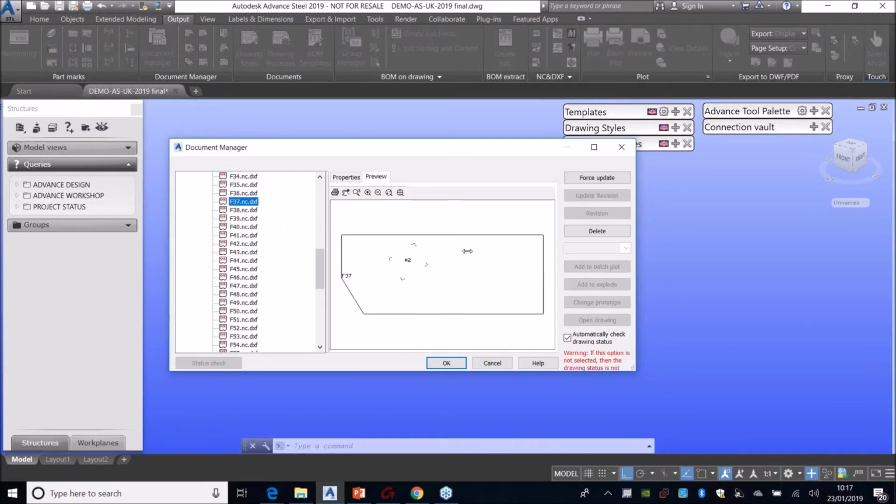All right, so it's not necessarily a base plate, but we do see an intersecting member, rectangular hollow section, and we see the main part reference scribed on this piece as well. So if you do not want any scribing of a main part mark or its signature block reference associated to the plate, then you'd probably want to output based off of the single part marks.